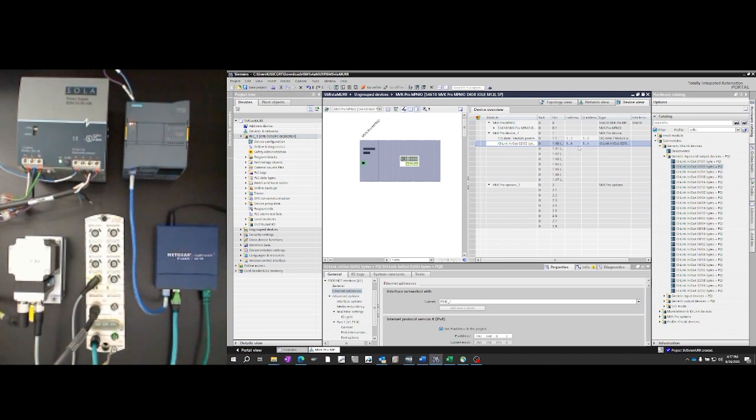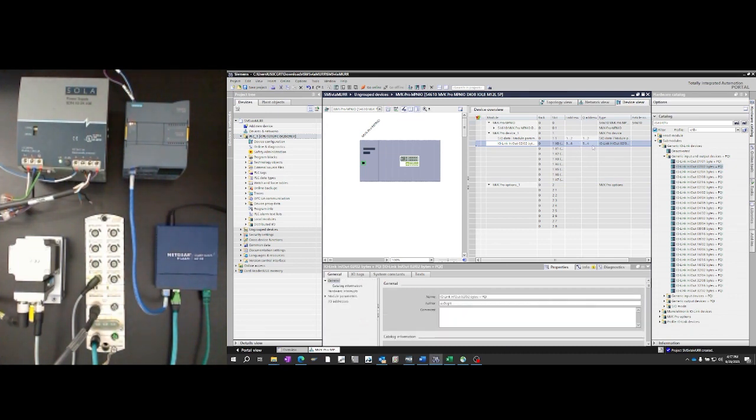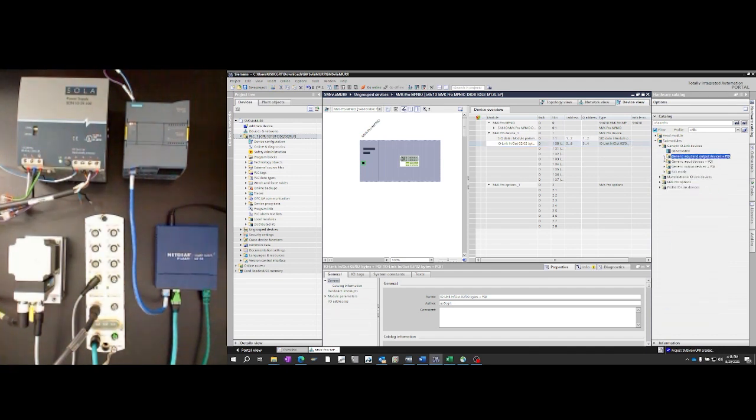Notice that the addressing allocates 4 bytes in and 2 bytes out. 2 bytes out was expected. 4 bytes in is somewhat unexpected, as we will only be utilizing 3 bytes in. This is due to byte boundaries in TIA Portal, but it will not affect any of the function for that device. For the rest of the ports, as you can see, nothing is connected to them.